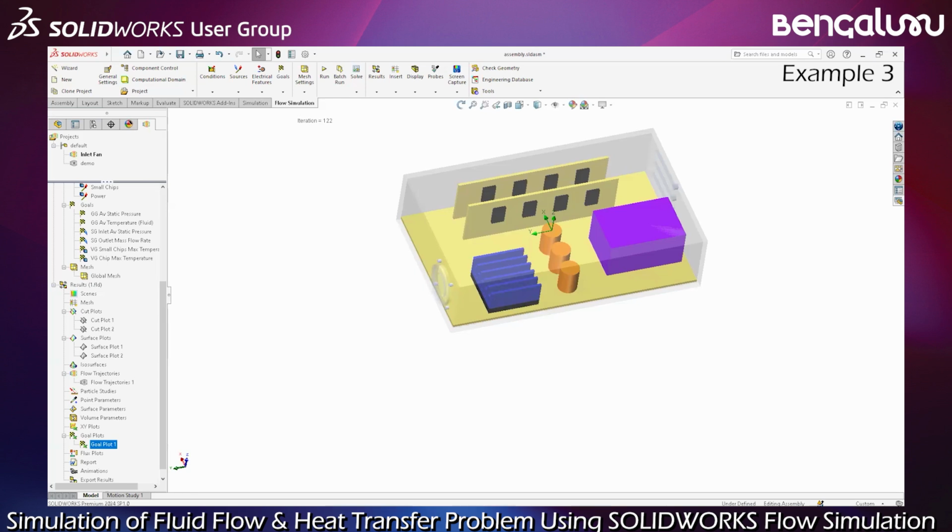There is a question: would you be able to share a resource on where the CAD, mesh, and pre-processor Boolean options should be used, or how these options affect the solver? So there are two things, let's say. Flow simulation can use the CAD Boolean operation from SolidWorks. As you know, Flow Simulation is integrated in SolidWorks. When it detects or extracts the fluid domain, it needs to do a Boolean operation.